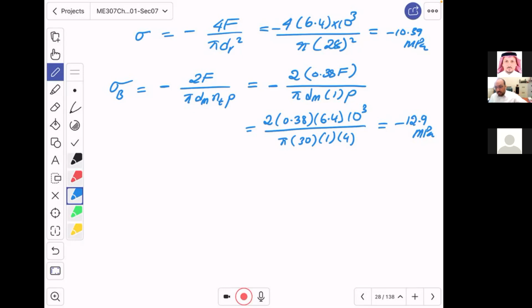So then, we were asked to find the stresses at the root. Now, at the root, we have one important stress, which is what? The bending stress. Why? Because at the root we have sigma bending, but we don't have tau, which equals 3V over 2A. It is maximum at the center; at the root, it is 0. That's why we don't care about it. So whenever you are asked about the root stress, you have only one.